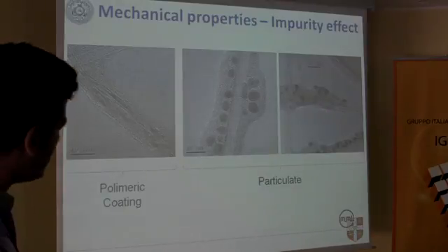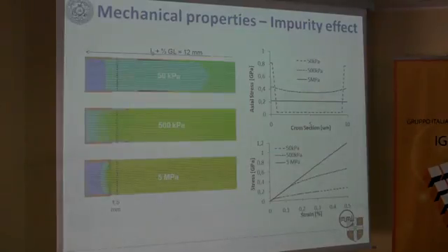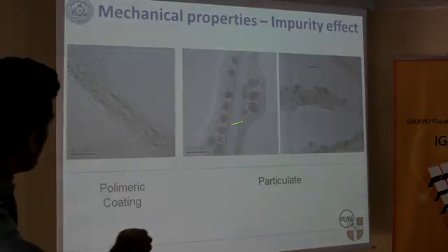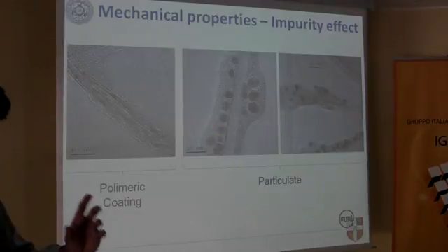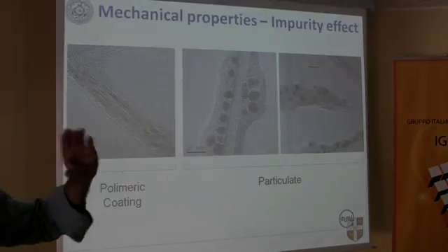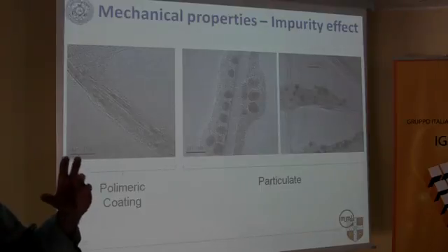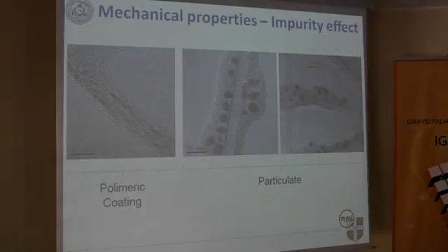Even if the density of material is getting lower, if I apply more pressure, I will not have more shear stress. But if I trap these particles inside my clamp, they will have an effect like sandpaper. So we can pull more material.